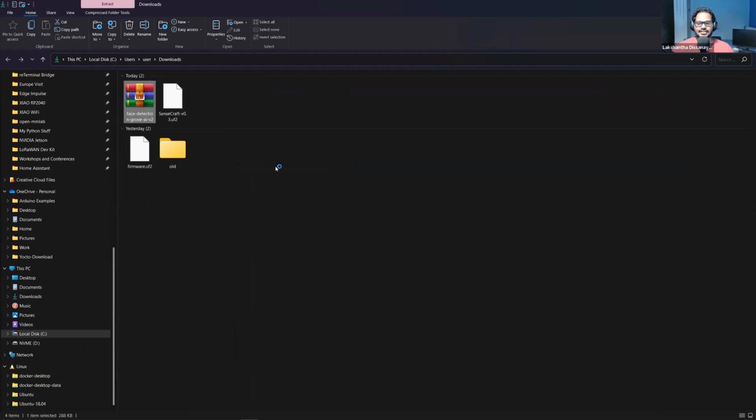So when we extract it, we can see a .uf2. This .uf2 contains the firmware and the object detection model, both in one single file. So you just upload this UF2 into the Grove Vision AI module, and then you can do the inferencing, right? For that part, I will show you this one. This would be the drag and drop like you had demonstrated earlier, right?